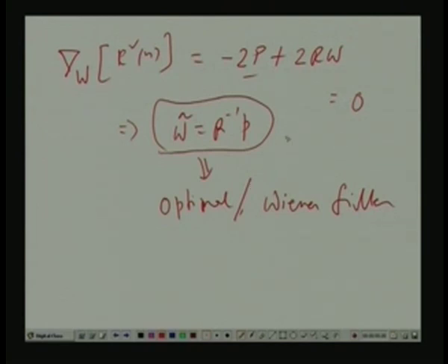It will further learn from the data and readjust itself, so that you get a new R and new P, and you get another corresponding Wiener filter. So, there will be a continuous adaptation mechanism. If the input R and P change, it will track, and it will have an iterative self adjustment procedure, and every time that iterative procedure should converge at the corresponding Wiener filter.